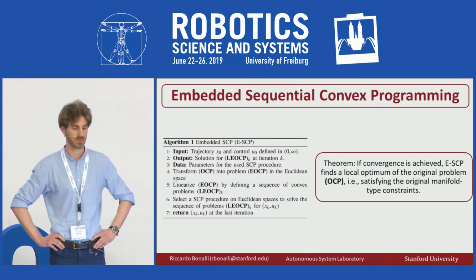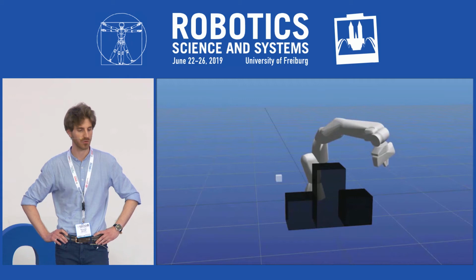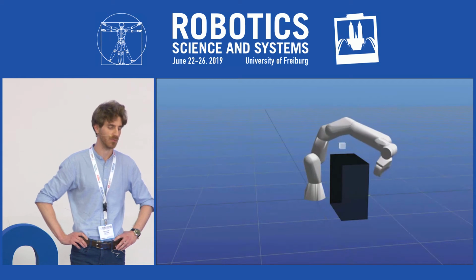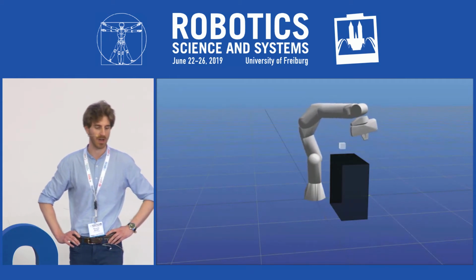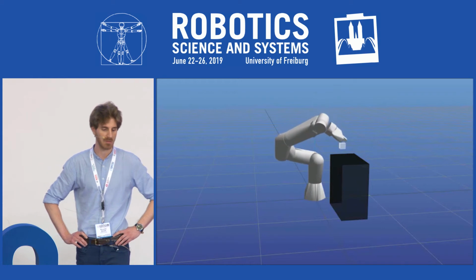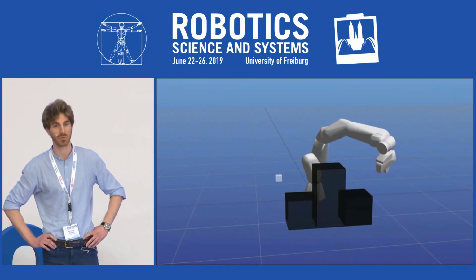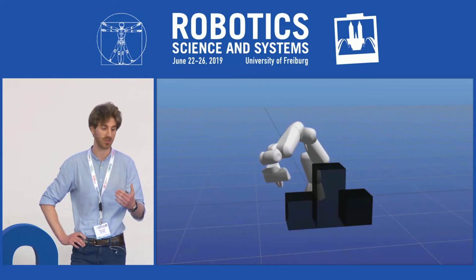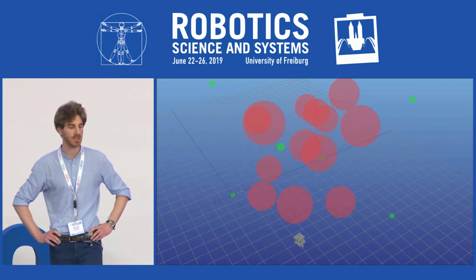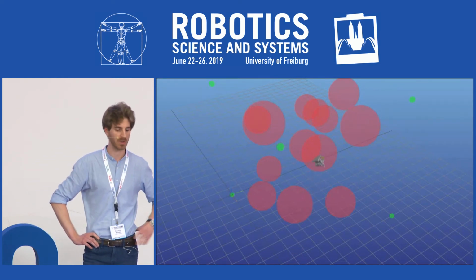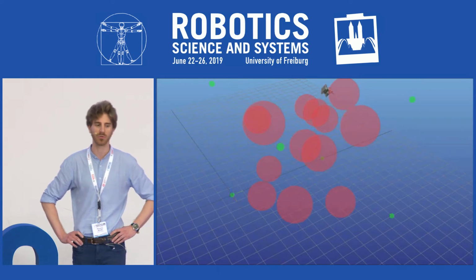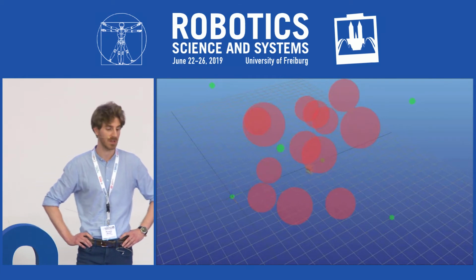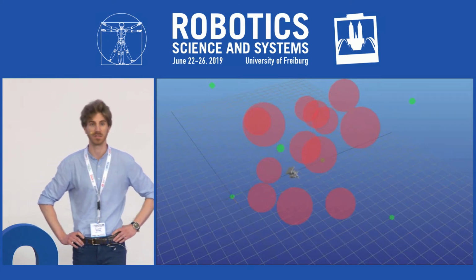strong geometric sense. We apply such a framework to several robotic systems, showing that we run faster than common state-of-the-art algorithms such as TrajOpt. The theoretical analysis we provided gave us some key insight to further accelerate this procedure. Indeed, we were able to exploit the convergence of the related Lagrange multiplier to leverage an indirect shooting method to accelerate even further.